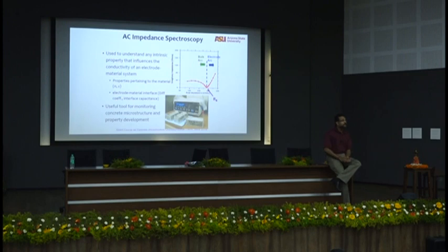Where are the ions in a cement paste? In the pore solution, the pores. So if the pore solution is very direct, between top and bottom is just one cylinder, the conductivity is going to be very high because the ions can conduct electricity very fast. Whereas if the pore structure is really tortuous, the ions will have to conduct through all these tortuous paths, your conductivity will be less. So you use that as a measure of how tortuous your pore structure is.